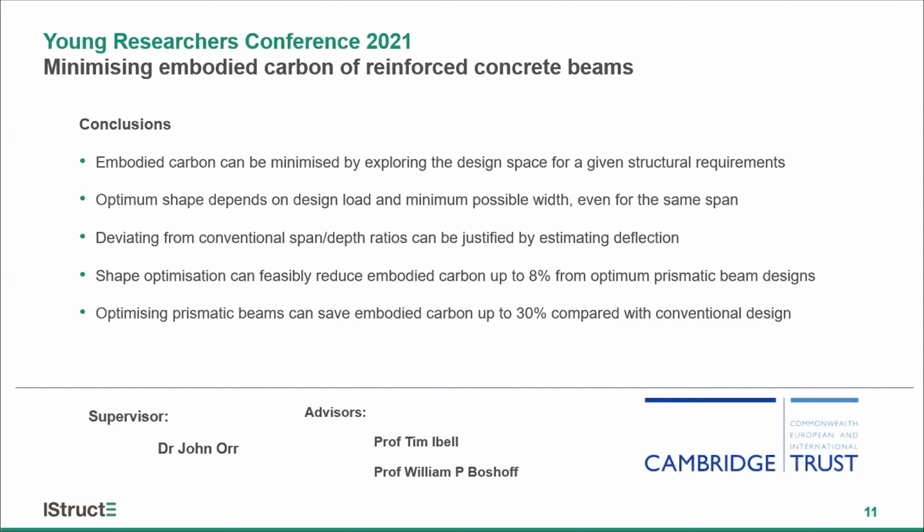You mean the carbon intensity of the construction approach, I guess? Yes. I think in those terms, this would be beneficial compared to conventional formwork as well, because we are going to use a fabric, and that is also reusable, and also the amount of formwork we need is less. With timber formwork, we can reuse it fewer times than the fabric. In those terms, I think we can safely say that this kind of construction technique will have lesser environmental impact compared with conventional timber formwork.